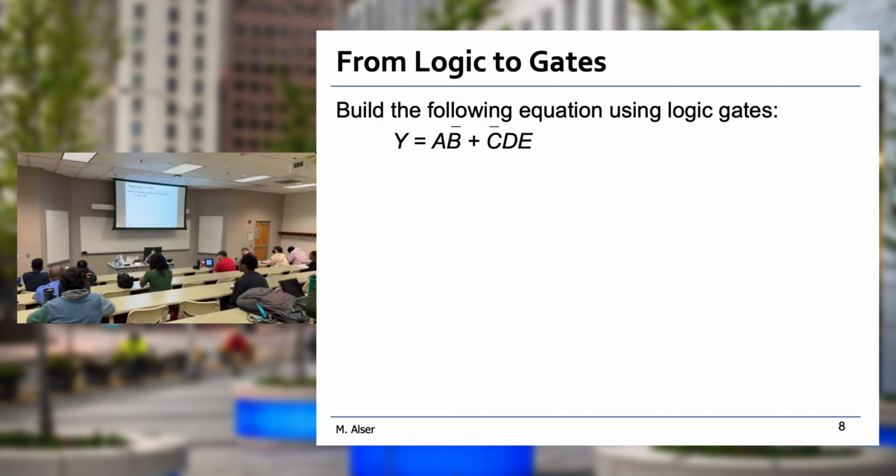It's up to you. If we have a restriction in the question and we ask you to use only 2-input gates, it means only 2 inputs to any of those gates, regardless of what the gate is. Now, if this is the question and this is the restriction, then we cannot use this way. We cannot assume a 3-input gate. We need to split them into 2 gates. So if this is AND, we would draw it first. We consider 2 inputs.